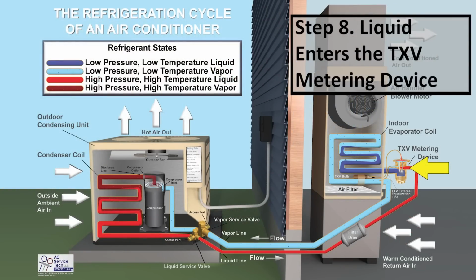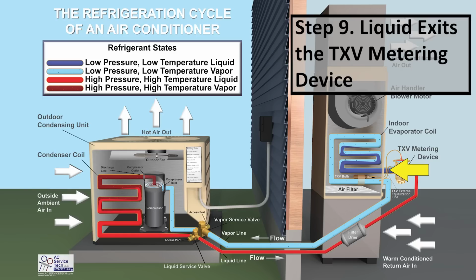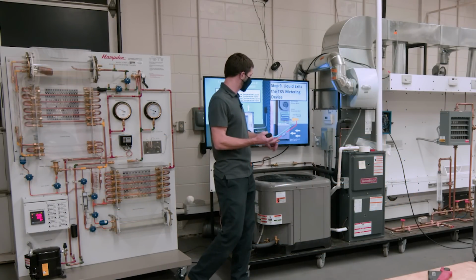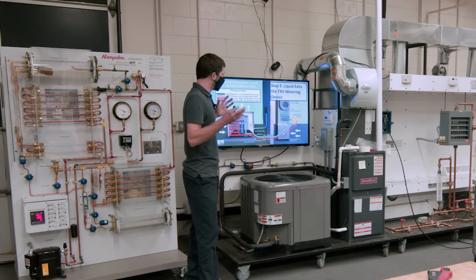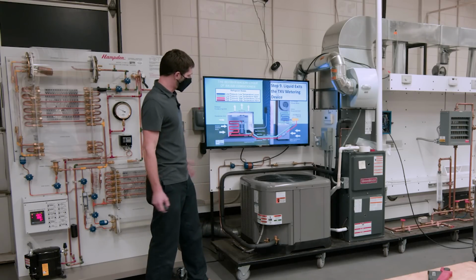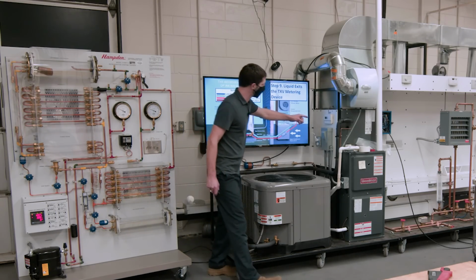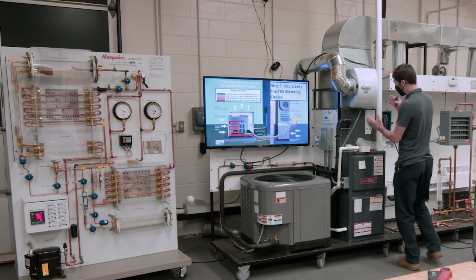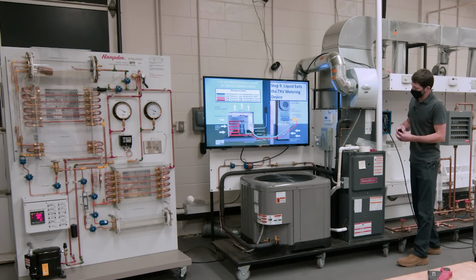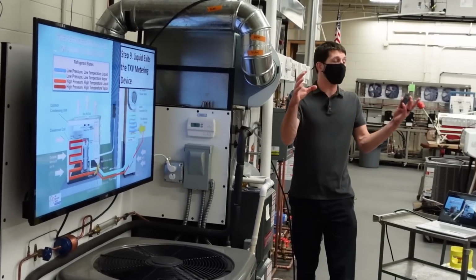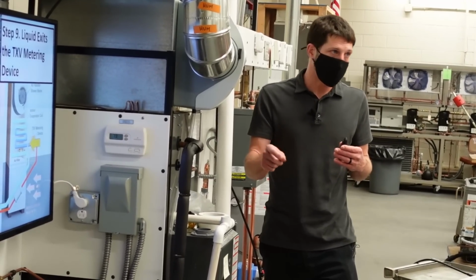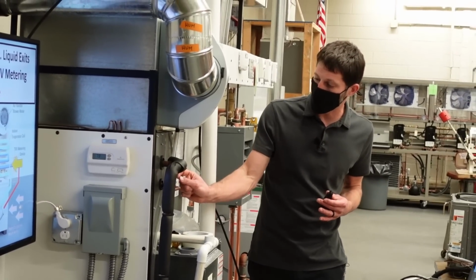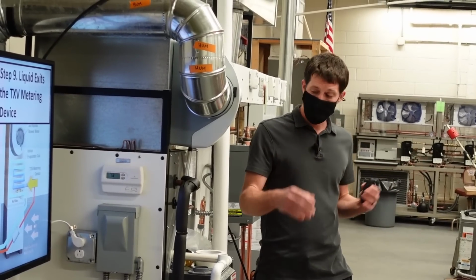Anyway, so you have high pressure, high temperature liquid refrigerant entering the thermostatic expansion valve. The metering device, whether a piston, capillary tube, so those are both fixed orifices, or a thermostatic expansion valve, they're all lowering the pressure of the liquid refrigerant. And when you lower the pressure of the liquid refrigerant, as soon as it enters this evaporator coil right here, what's happening is there's an availability of space now. So there's extra space, and so it's not just going to be liquid. You're going to have maybe around 20% as a flash gas, a gaseous refrigerant, and the rest is all liquid.